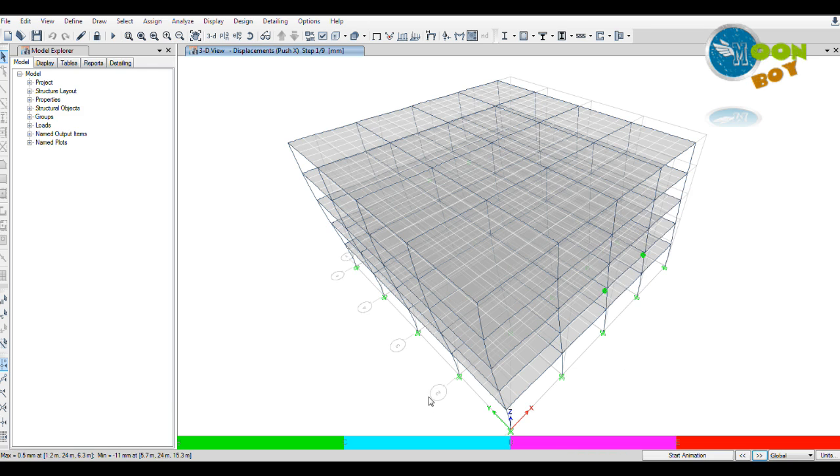First at the green zone, it is between B to C zone and C to D and D to E. E is a breaking point of the hinge. So at E, the building will collapse. B to C is the green zone if you see the hinge diagram. So in the push X direction, we can see step 1 to 9.